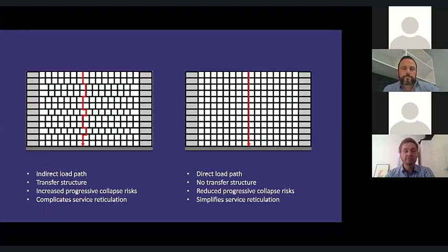Yeah, so I think for hotel buildings, they really lend themselves to something that has a direct load path more often than not. Generally, from an architectural perspective and an end user requirement anyway, you're not going to want a hotel to have various layouts floor to floor. It just doesn't make a lot of sense from a logistics and service perspective. But if it is possible to have transfer, and we've certainly achieved that on some projects, not a hotel, at an apartment building recently.